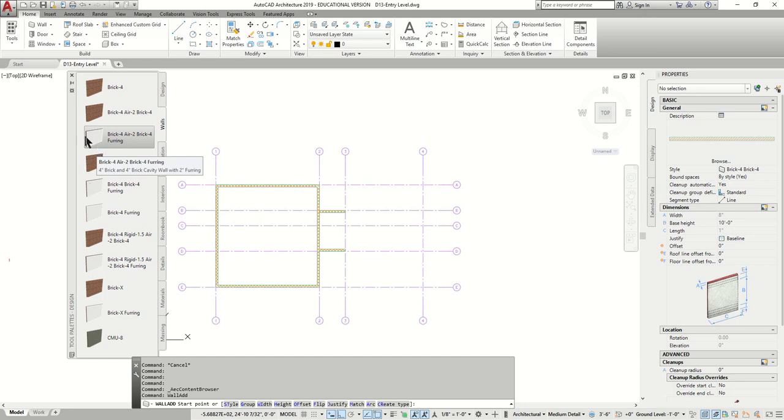So now before we start, we have to just check our parameters again. It's a good habit to check before you start drawing. So we see that our width is 8 inches, which is okay. But our base height, we have it at 10. We don't want a 10 because that's the same as our exterior. So we want to go 1 foot below. So we're going to type in 9 feet. And for justification, we're going to go to the center of the object.